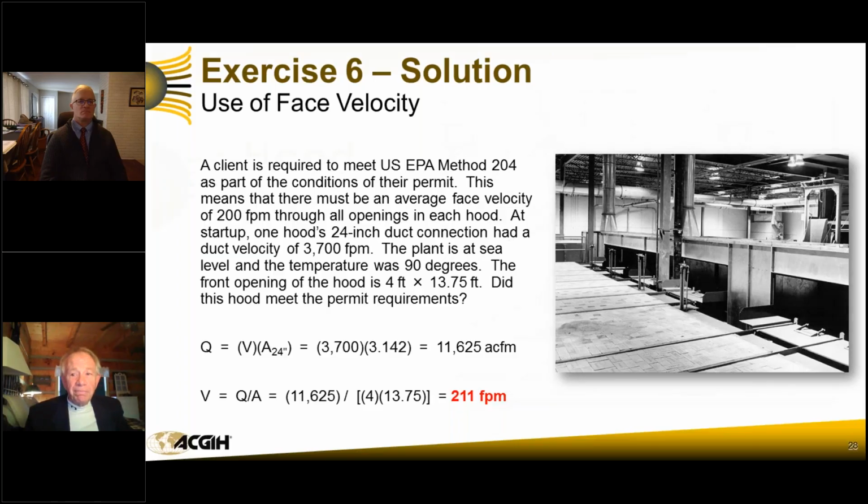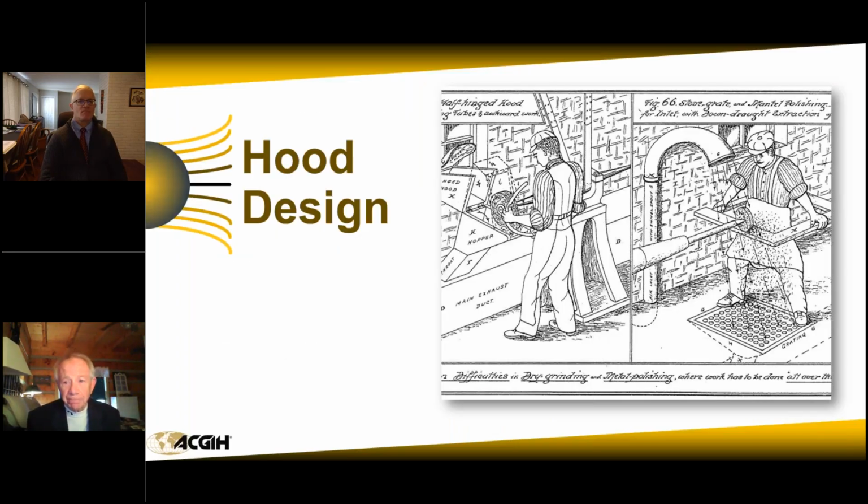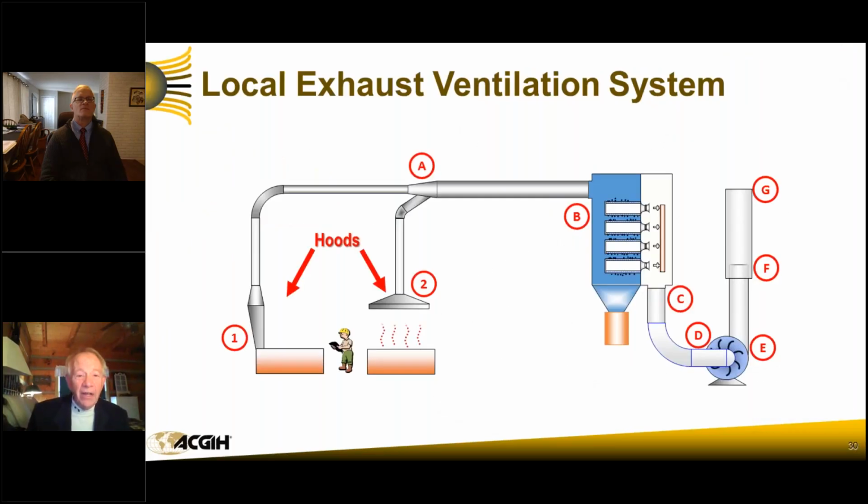All right, let's talk a little bit about hood design. Hood design is my favorite part. Other than the fans, it's my second favorite part. In this case, we've got a fella here that's grinding, and this wheel is slinging the dust up. We notice that, fortunately, this high-speed buffer polisher is only throwing the dust up at his apron top. There's no way possible that can reach his breathing zone. I'm not buying that. Here's our local exhaust ventilation system. Let's get it started. Somebody bump that fan. Okay, we bumped the fan. We're talking about the hoods.